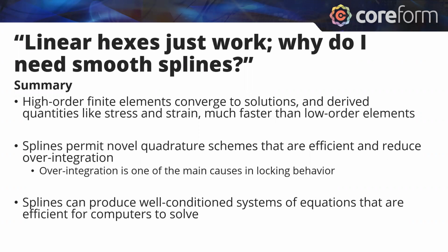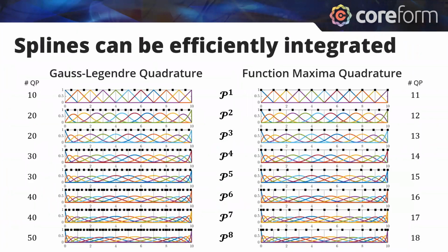Thank you. And then are they computed for a patch or per Bezier element? Yeah, so these are computed on the patch level, essentially. So they're computed from the global basis function point of view. If you look at the picture here, the squares are the quadrature points, but if we were computing them per element, they wouldn't be at the maxima of the global basis functions like this red function here. So that's where we're computing them.